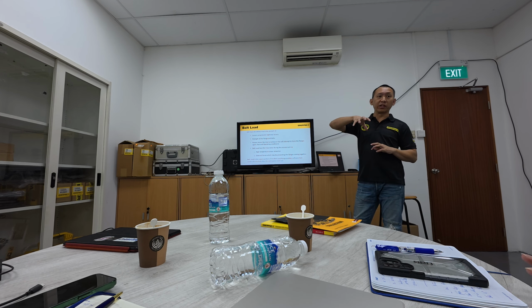Things like torque multipliers have a factor to increase the torque, and we can calculate it based on the tool specification, the input and output. There's a ratio. We know this from the manual torque wrench too. For a pneumatic torque wrench, we can set the input air pressure and from there calculate the output torque.